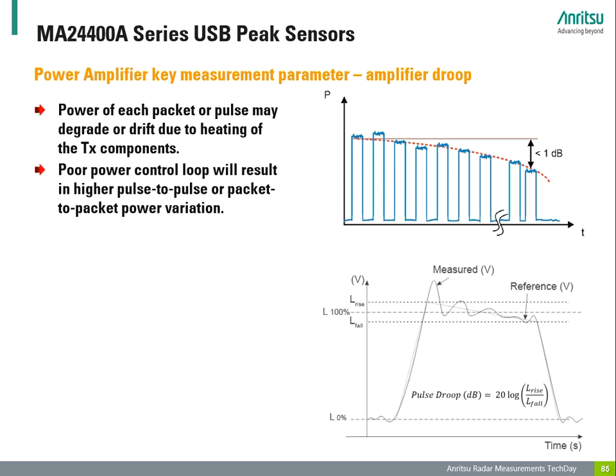Gallium nitride has an inverse gain relationship with temperature. The thermal response of the transistors reduces the gain by 0.5 to 1 dB, depending on the temperature rise during the pulse. The droop is compounded with cascaded transistors, resulting in a further reduction in output power.